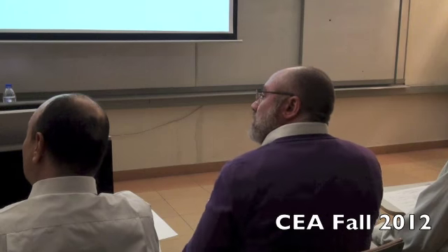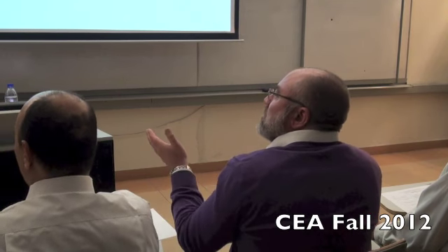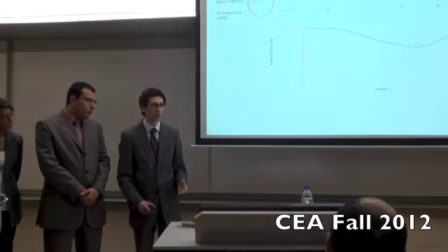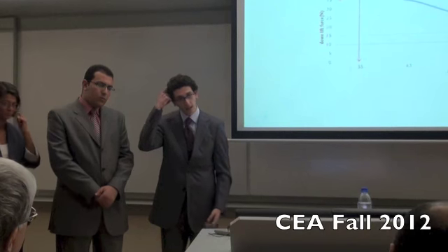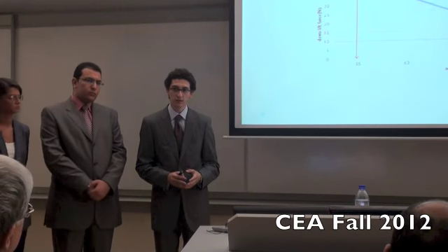You should consider designing for higher wind because this might not actually be the case. We're abided by the map. We got it from the International code. Any international code is more stringent than what we have. The code specifies a very high wind speed, but we found it specifies a default speed. But we were told that if we had a specific wind speed for this region, we should use it instead of using the default.